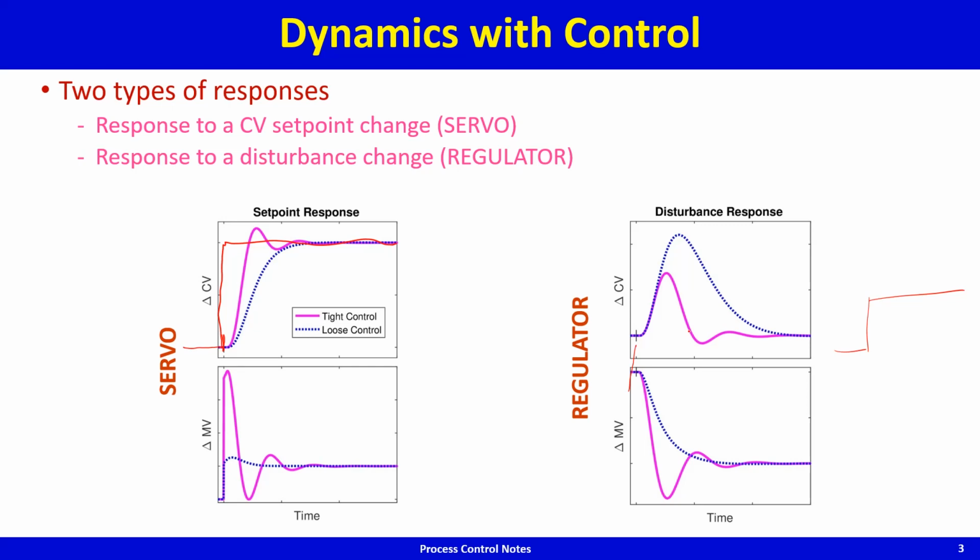Every person is a 50 watt bulb. The body generates that much heat. So suddenly, because of so many people walking into a confined space, the temperature of that confined space will start to go up. In response to that increase in the temperature, the controller will reduce the heater duty,